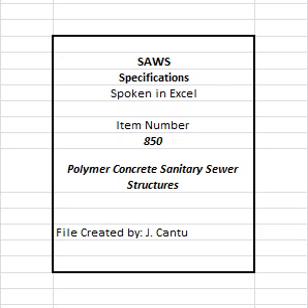21. All materials needed for grouting and patching will be a compound provided by the manufacturer or as recommended by the manufacturer. 22. The structure ring and cover shall be of ductile iron construction. 23. The cover shall be solid with no vent or pick holes, hinged with underlying special hinge area leakage protection, the cover secured with 4 stainless steel bolts, and shall have a recessed pick bar for cover opening. A. Cam lock type covers shall not be allowed.